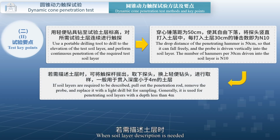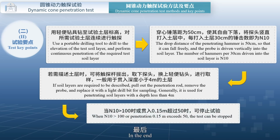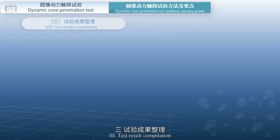When soil layer description is needed, the penetration rod can be extracted, the probe removed, and replaced with a lightweight drill bit to conduct sampling. This test is generally used for soil layers with a penetration depth of less than 4 meters. In the end, when N10 is greater than 100 or penetration exceeds 50 blows per 0.15 meter, testing may be stopped.